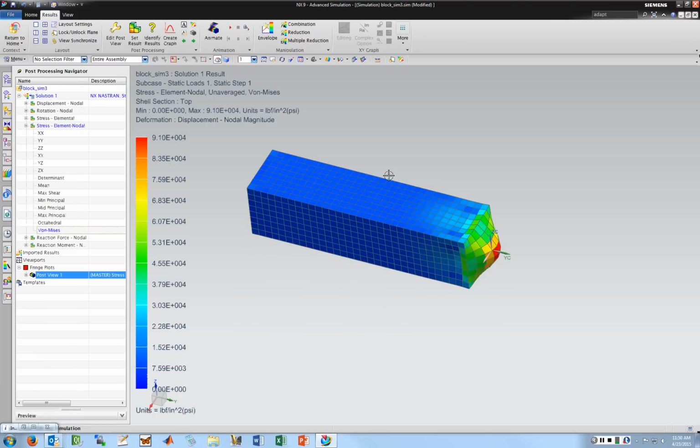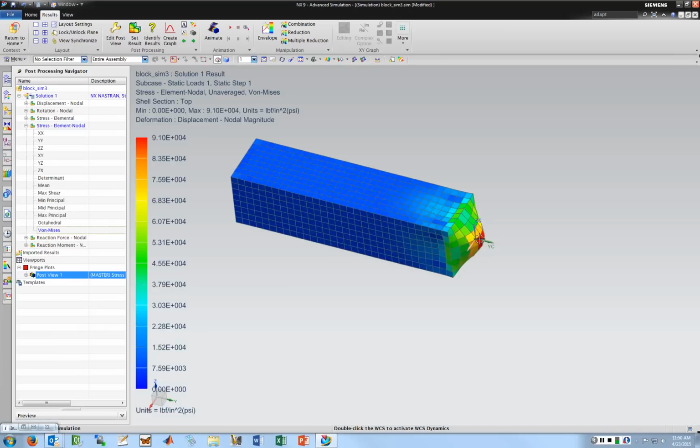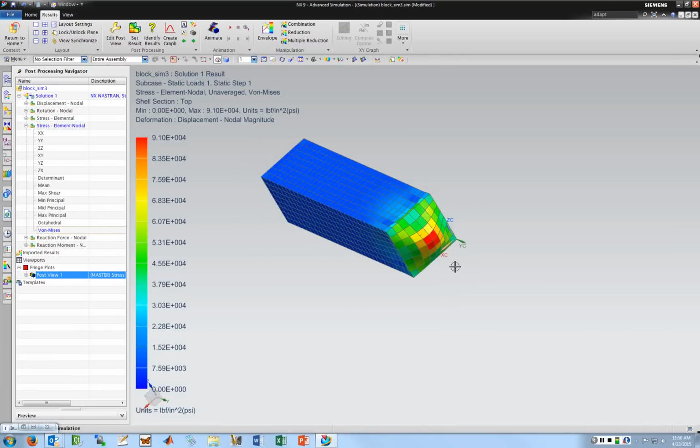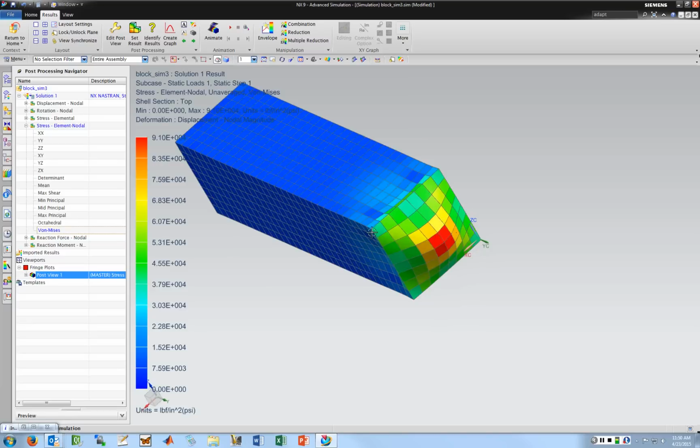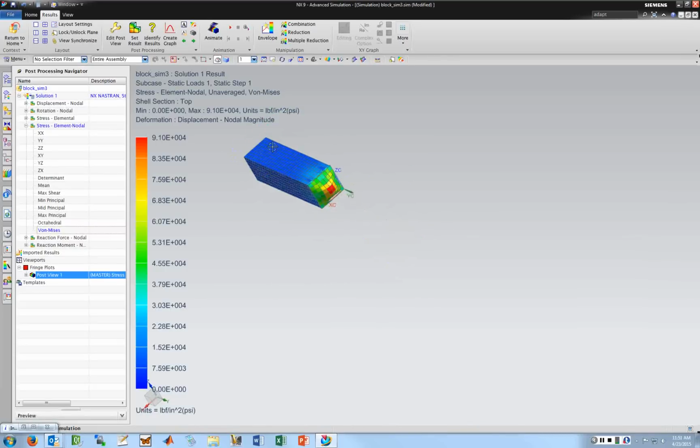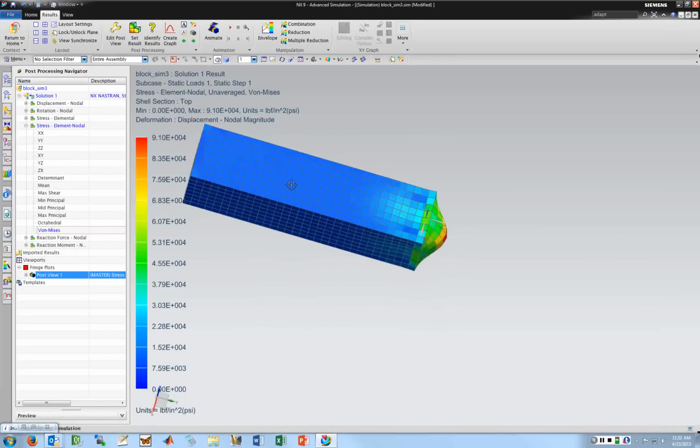Okay, so I want to go to my results, I want to check, let's do elemental nodal so I get the blend. And you can see the strain's exaggerated. So I put 1,000 pounds force on it, what it does is it takes that force and it divides it by all the nodes and then applies it to the nodes. Since these nodes around the perimeter are supported by what would be the edges of this box tube, and this would basically be like a 16 gauge plate welded onto the end. If I put that load distribution even across, then yes, I would expect it to kind of balloon out like that. So that deformation makes sense. It is exaggerated. Always remember that this is exaggerated. In no way would it stretch that much in the real world.